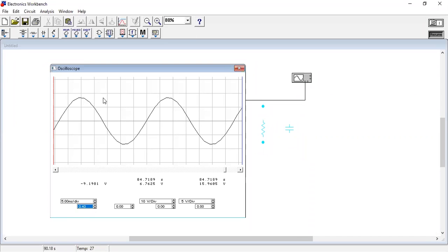Okay, so 6 boxes is 30 milliseconds, and 6 parts is 3 milliseconds, so 33 milliseconds. Okay, the time difference between these two peaks. And this one time value is used to calculate the frequency. So you can put the frequency value: f is equal to 1 upon T. Now we find the voltage value also.